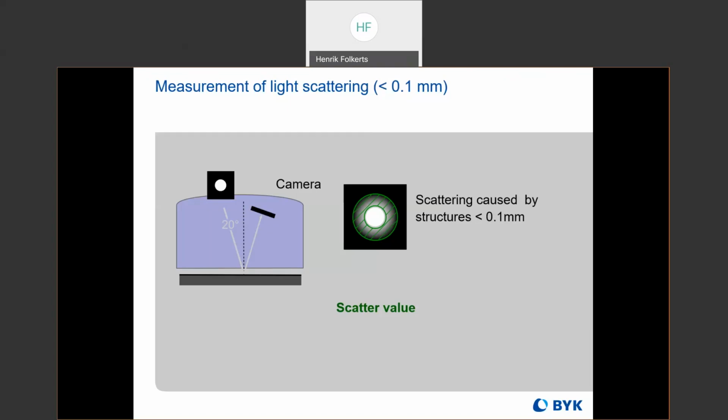I know that we worked on a project with GM where the fascias, because of that micro crinkle in the substrate itself, caused the R value to be lower. And I think on most plastic parts, it's going to be a bit lower for the R value specifically. And you have to remember that these are calculated values that the OEMs decided that they wanted to use. We didn't necessarily come up with the calculations. We just matched what they wanted. So, I think that's really important.